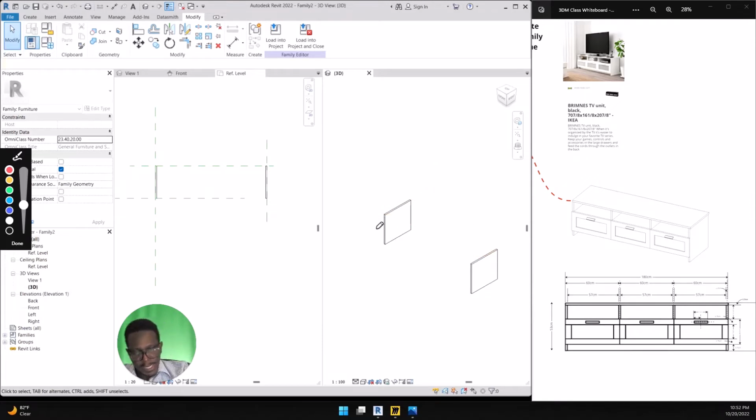The trick with this is that we need to let our work plane now be the surface on top of these walls, because our work plane is currently down below, because we used our work planes to create the base of these objects and then extrude them up, and we created the base of this object here and then extruded up.